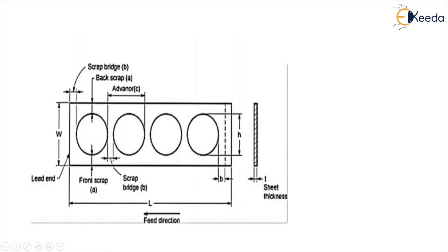This distance is known as the scrap bridge. See, this is the scrap bridge, or the distance between the blanks that are going to be produced is the scrap bridge. And this gap or distance is the front scrap, and this distance is the back scrap. So here we are going to have the front scrap as A and the scrap bridge as B.